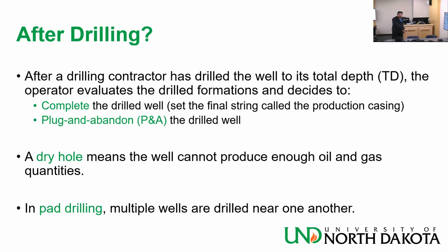And then another well here, and then I will switch to oil-based mud, go back into this well, drill the horizontal, then walk the rig back here, go back in, drill the horizontal, and then go back to where you are, drill the hole. Then I have 3 wells here, I have 4 wells there with a different rig. Drilled in about the same time.